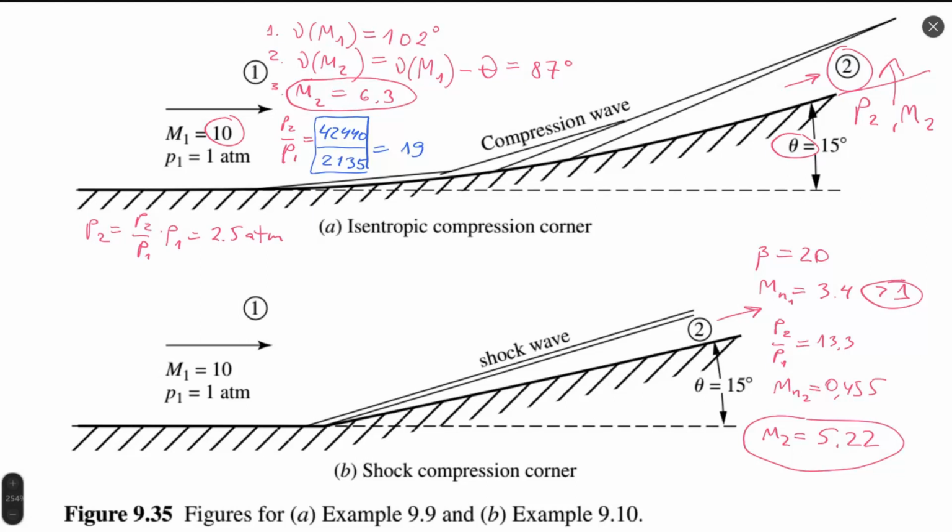But already had this attention because pressure ratio of 2.5 corresponds to just simple supersonic flow, does not correspond to hypersonic flow. And this also has to be confirmed. Every time you receive some value, think how you can check. If possible, make a double check, if possible, compare with some other solution.